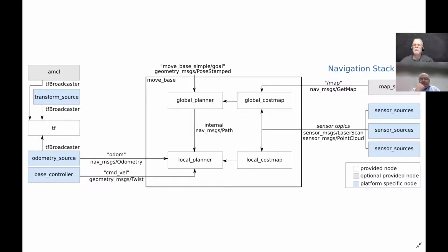So the next time you come in, instead of starting up SLAM, you start up AMCL, and you tell it the map that you just created. Then it takes the laser scans and the map that you created, and AMCL sets your localization and keeps you lined up with the world. That's what the map server does. So there's various things you can do with the map server.